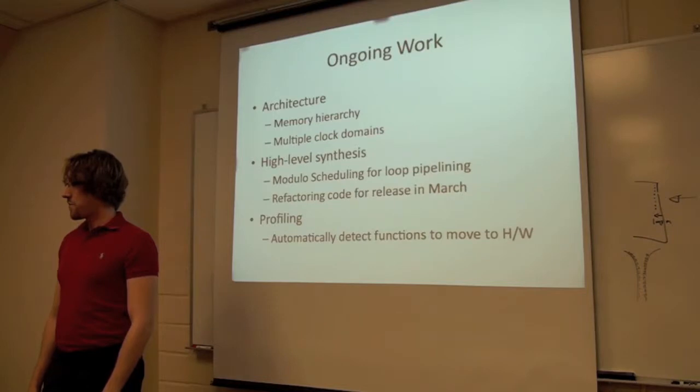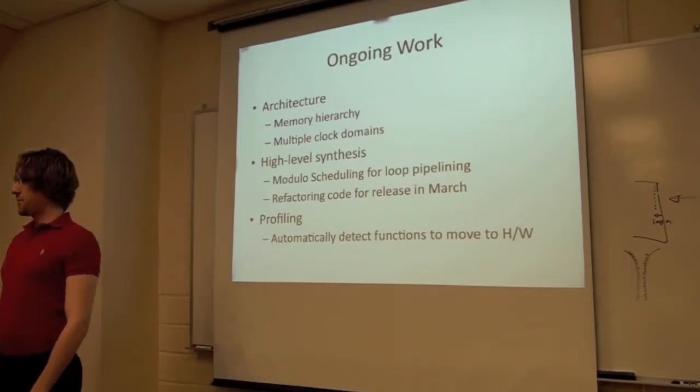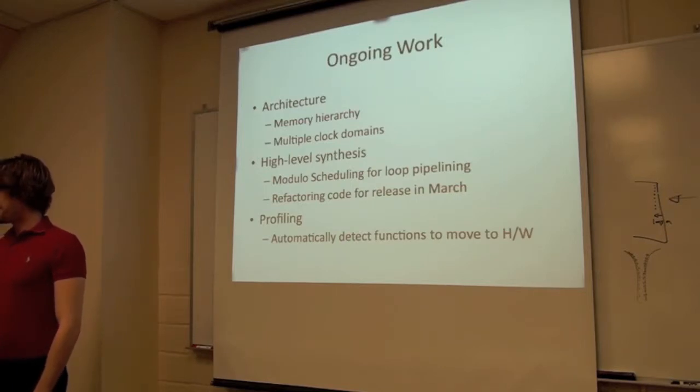So if you're running it at 300 megahertz, that's what you get, 300 MIPS, million instructions per second, because IPC is around 1. I just wanted a back-of-envelope comparison with Tiger MIPS. Assuming that IPC is 1, which would probably need dynamic branch prediction, instruction cache and data cache. It does have an instruction cache, data cache, and branch prediction.